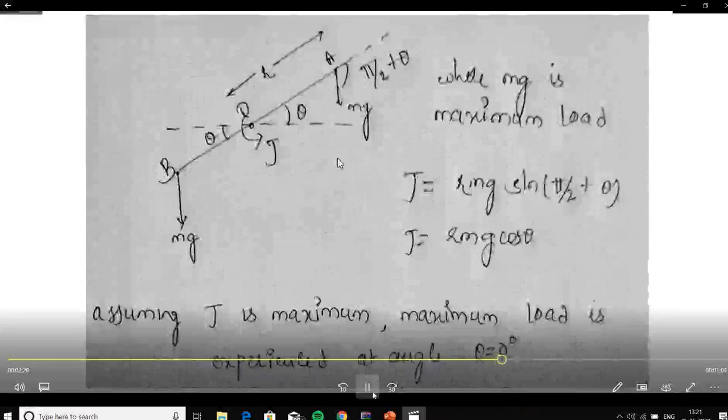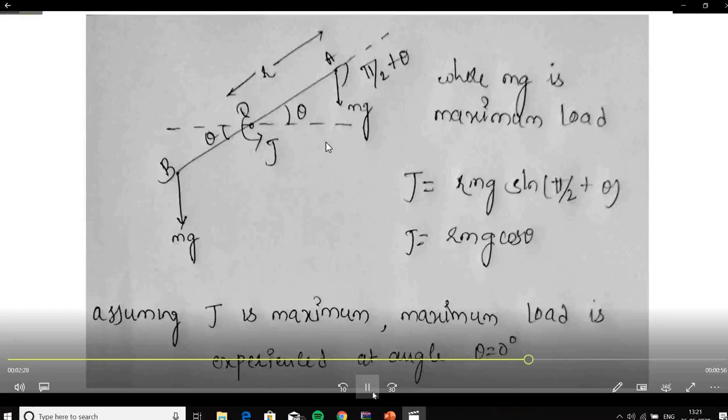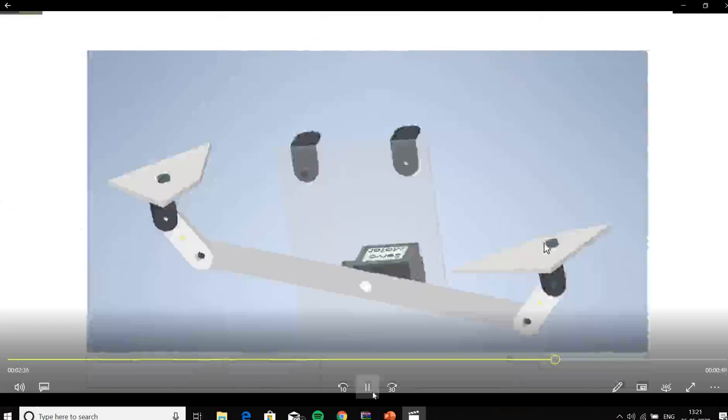We don't think that our load will exceed more than 50 grams, including the duck, nuts, base, this gray arm, and the L clamp. Since we have ignored friction, and since we are left with a margin that can be handled, I think that our servo will overcome that friction and will function perfectly.